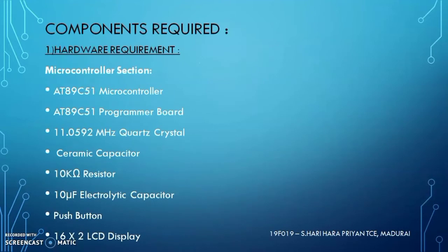And the components required. First, we see the hardware requirement. In the microcontroller section, there is an 8051 microcontroller, which is an 8-bit microcontroller, AT89C51, and we need a crystal oscillator, ceramic capacitor, 10 kilo ohm resistor, electrolytic capacitor, push button, and a 16x2 LCD display to display the output.